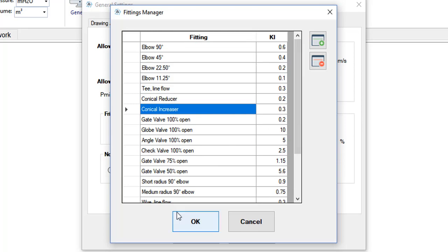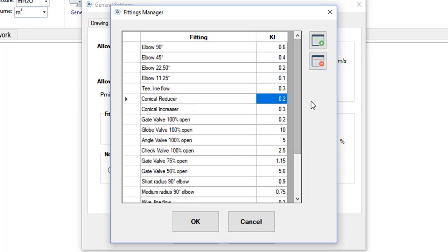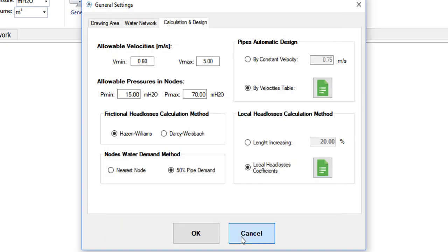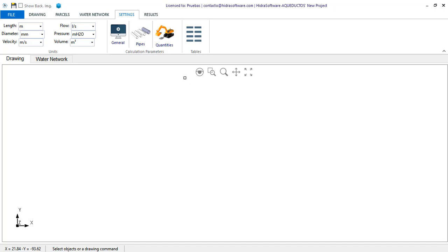If you need to manually assign certain fittings or accessories, you can create them in the table and then, in the Properties dialog of each pipeline, specify the number and type of them. In relation to what I commented previously, regarding the process of selection by the software of the diameters under the Design Velocities options, you will see that you have in this Configuration tab the Pipes button.